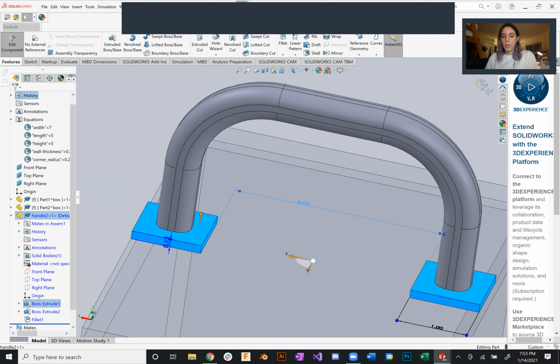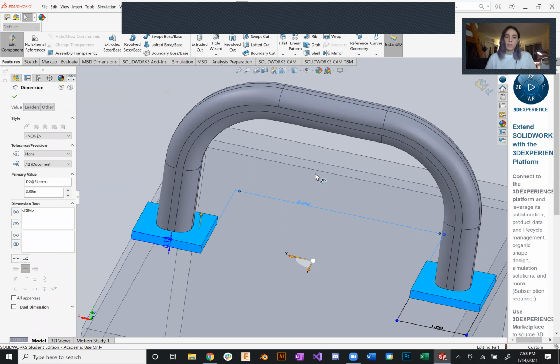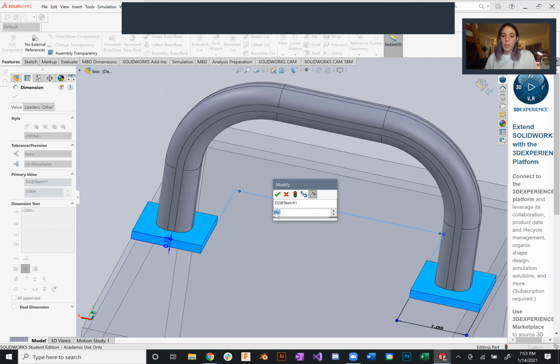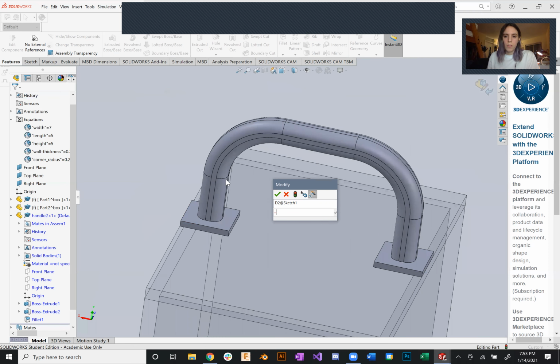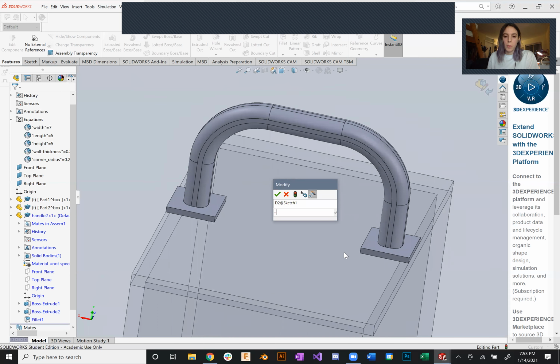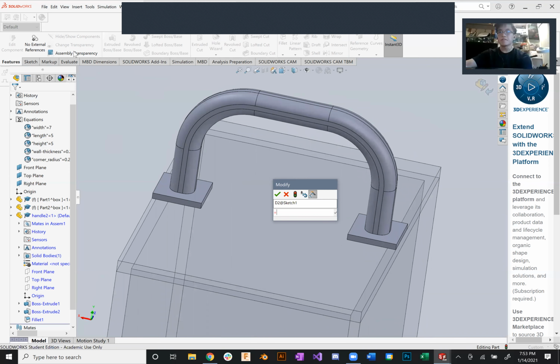So if I double click on this width 3, it's going to think about it for a good long while. And then let's set this in context of the assembly. So let's set this equal to, firstly, width. I believe, did I make width longer than, I don't remember which one's width, but. Width is the longer one. Width is the longer one right now? Okay, so I want to set it to length, right? Because I want to keep it so that it's not too wide. So I'll grab length, and then I'm going to just do length minus 2 inches. We'll give it a good margin.